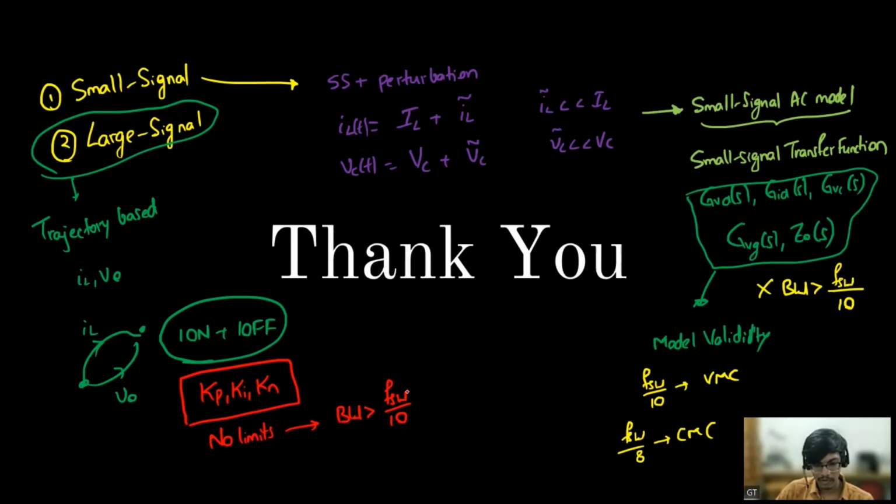With a bandwidth greater than FSW by 10, which cannot be done using the small signal model, because the model itself is not valid. Say I want to use some model and the model itself is not valid, then I cannot use that model, right? So for a bandwidth greater than the switching frequency by 10, this model is not valid, so I cannot use this small signal model. I have to rely on some other model, which is the large signal tuning, where we consider the entire ripple information, everything, and we do not consider any assumption. And we shape the trajectory.